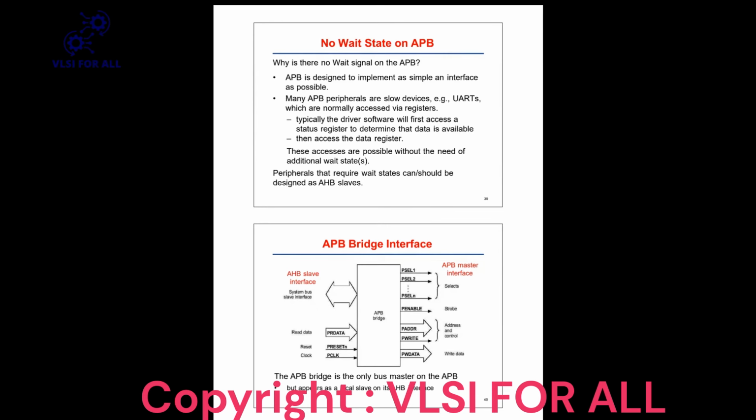But if you are dealing with wait state, and basically with wait state only we have to go, because personally I have worked on projects where we had to wait till the time the slave gets ready. We had to wait for the ready signal to go high or low, and that status we had to check. And even if you start working on this APB project, or create a test bench and all that, you will also go with wait state only.